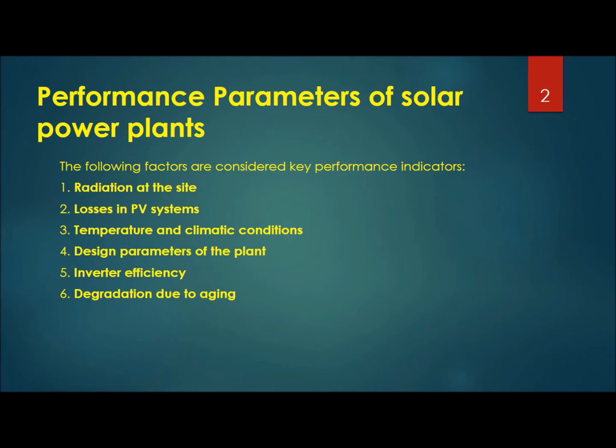The following factors are considered key performance indicators: radiation at the site, losses in photovoltaic systems, temperature and climatic conditions, design parameters of the plant, inverter efficiency, and degradation due to aging.